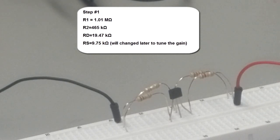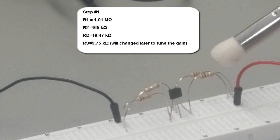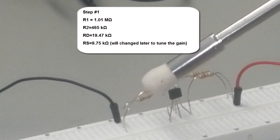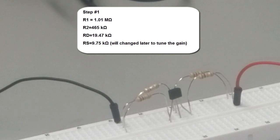Then I have RD. RD is supposed to be 20 k. I got 19.47 k. And I finally have RS over here, and RS is supposed to be 10 k, and I end up getting 9.75 k ohm.